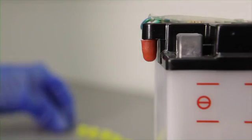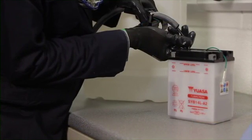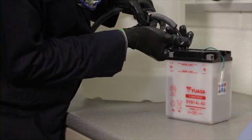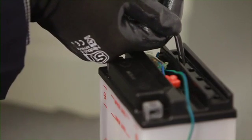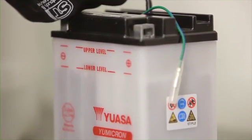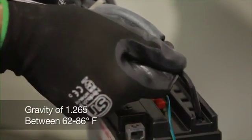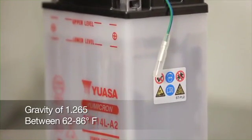Remove the sealing cap from the vent and throw it away. Never replace this after the battery has been filled with electrolyte, as it may cause the battery to rupture. Fill each cell with electrolyte to the fill level indicated on the battery case. Always wear protective eyewear and gloves when working with electrolyte. The electrolyte should have a specific gravity of 1.265 and be between 60 and 86 degrees Fahrenheit.